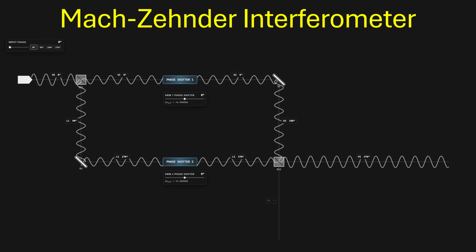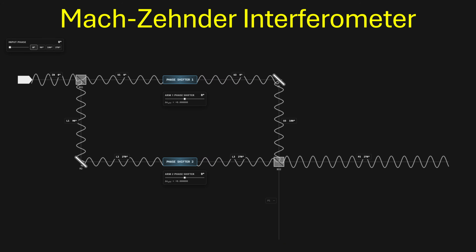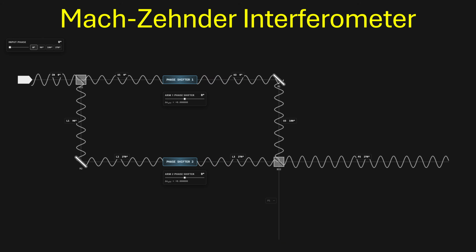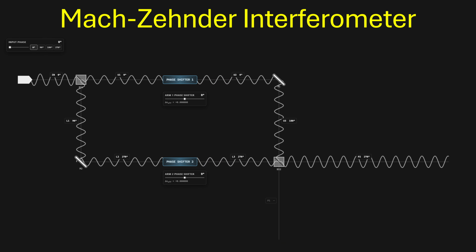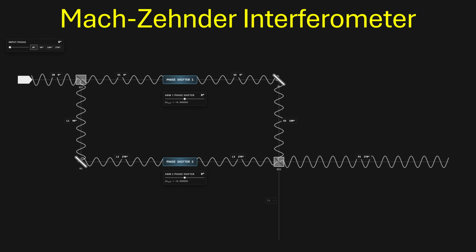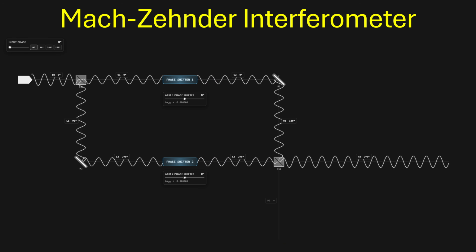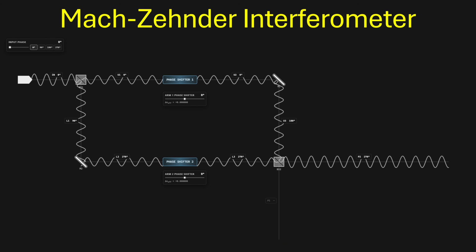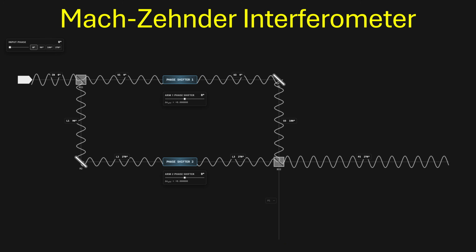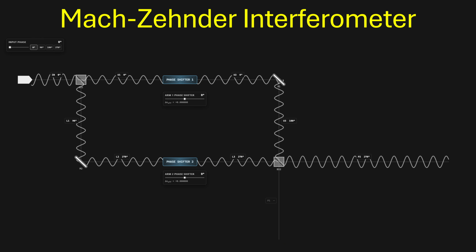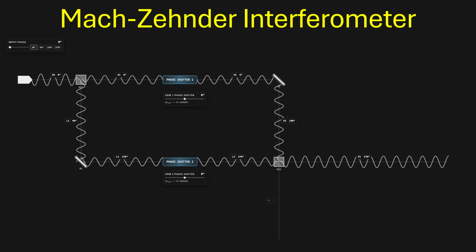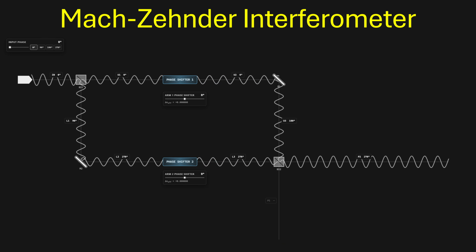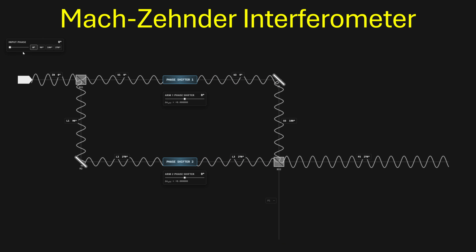In a Mach-Zehnder interferometer, 2 beams of light are interfered before they ever reach an optical sensor or a transceiver output fiber. The basic design divides a beam with a 50-50 beam splitter, phase shifting the lower arm by 90 degrees. After the reflection, they arrive at the second beam splitter 90 degrees out of phase. So when half of both beams are phase shifted by 90 degrees again in the second beam splitter, this makes one path combine in phase, constructively interfering, and one path combine 180 degrees out of phase, destructively interfering. You can see that so far, the resulting interference pattern is the same regardless of the input phase, so this is not a functional detector yet.